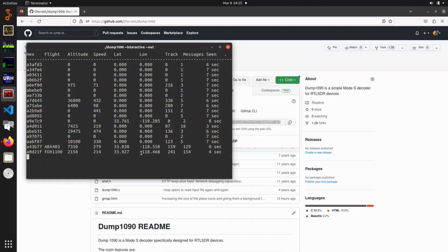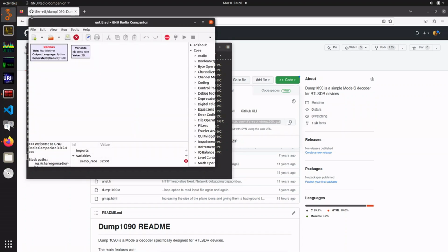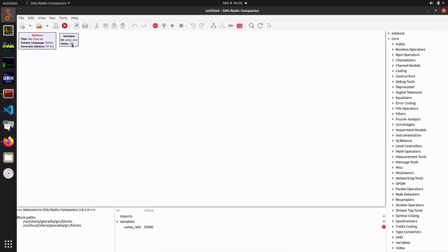So now what we want to do is inject some of our own spoofing signals into this stream. With your mouse cursor, come up to the top left corner and click on the icon GNU Radio Companion here. Go ahead and full screen this, and click on the button which is open existing flow graph.